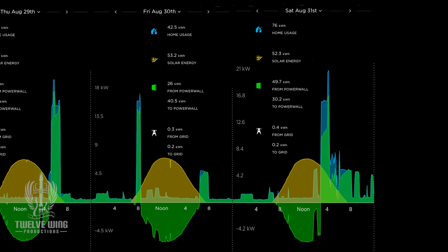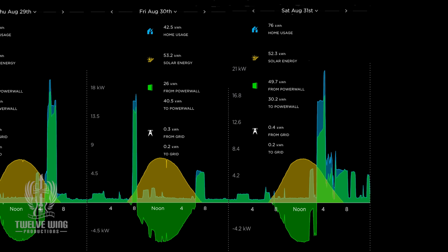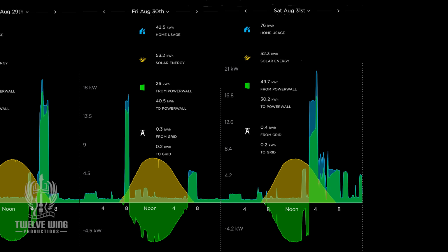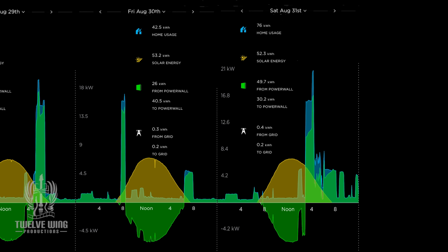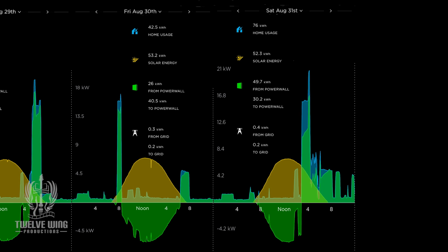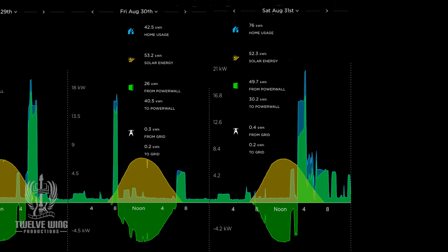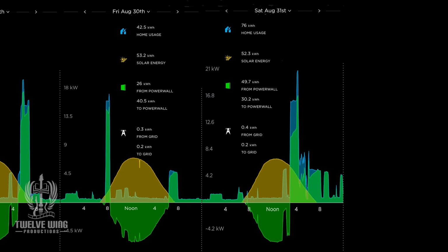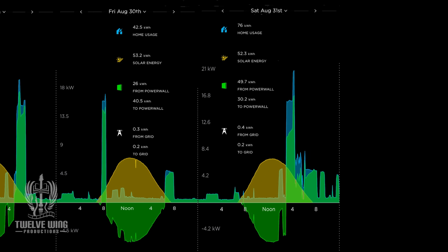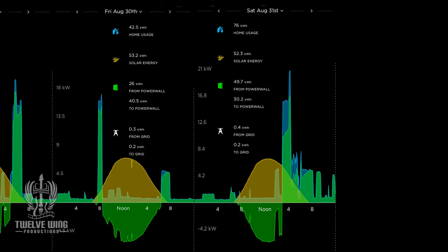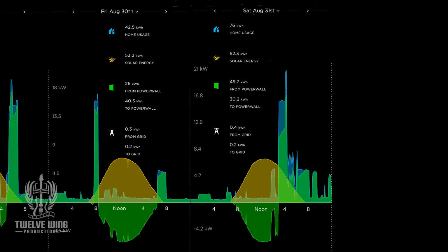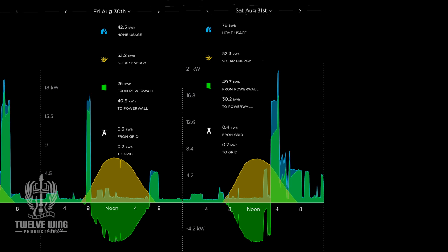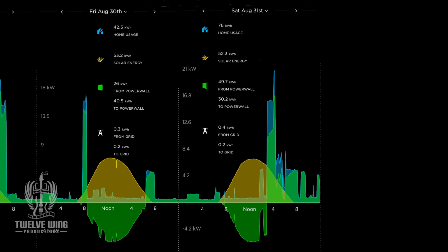And then you can see the system building during the evening. A little bit of an AC hit, looks like around 2:30 to 3 o'clock, something like that, and then obviously putting some charge into the vehicle, and you can see that two-layer spike there. It's the charge going to the vehicle as well as a bit of air conditioning use coming on at the same time, the tail end there.